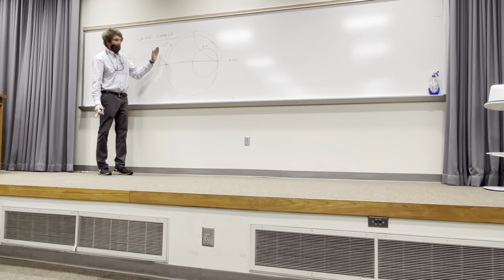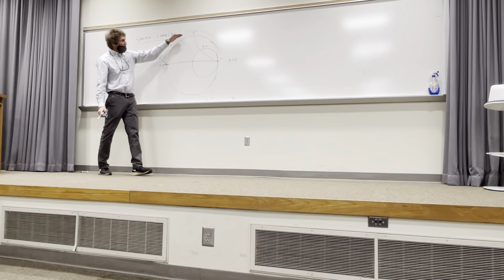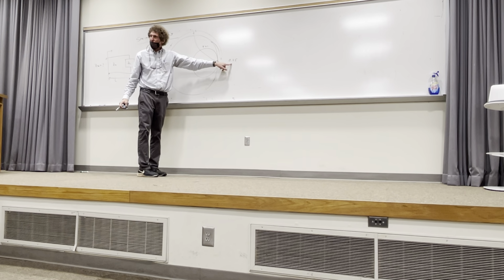Take a look at that wavelengths toward generator arc there. Can you all locate that? Now look, that's 0. You keep going all the way to here, you see 0.25, right? They might not have a lambda next to it. That means you went a quarter wavelength around. And you'll see this point has a value of infinity on it. Just follow me on that?